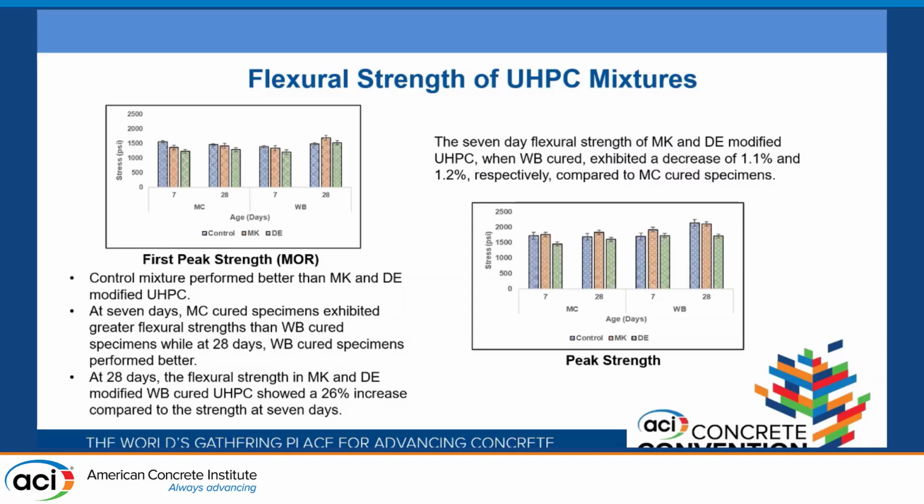At 7 days, MC cured specimens exhibited greater flexural strengths than WB cured specimens. At 28 days, the flexural strengths of specimens cured under WB showed improved performance, and the MK and DE modified UHPC mixtures at 28 days showed an increase of 26% when compared to 7-day strengths.